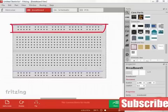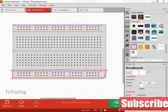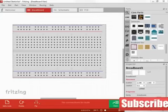Along the top and along the bottom, we have two buses. They are marked blue and red, or minus and plus, and are common through the whole bus. Anything inserted into the red or the plus bus will be connected, and anything inserted into the blue or the minus bus will be connected. These buses are handy to use as power supply rails or input and output signal rails.